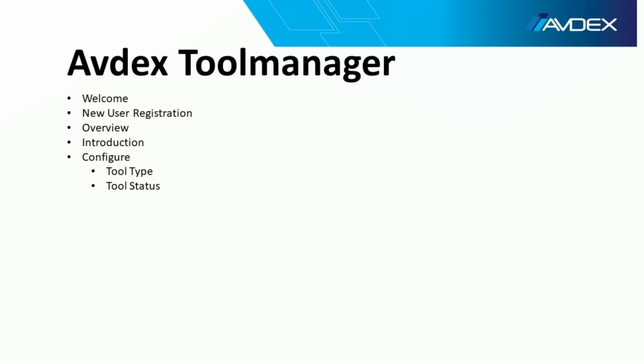Tool status. Tools may be flagged by their status. This has the advantage in allowing the user to quickly see the current status of a tool. These headings include serviceable, unserviceable, scrapped, missing and removed from service. The removed from service flag allows the retention of the history of the tool, while indicating that it is no longer in use. Tool status headings may be edited, added to or deleted, depending on the AMO requirements. Tool list may be printed by tool status by applying the filter in Tool Register.